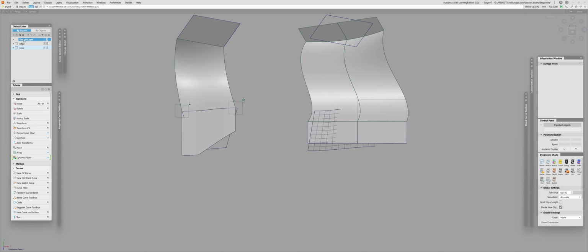When it comes to the skewing, the good rule of thumb is to align the surface as a skew before you perform the trimming operation. Otherwise, it doesn't matter how you trim it. If you trimmed it, your skew alignment is gone. You will not have the proper result. And the only thing you can do is, as I said, to untrim and align first, or trim convert your surface.